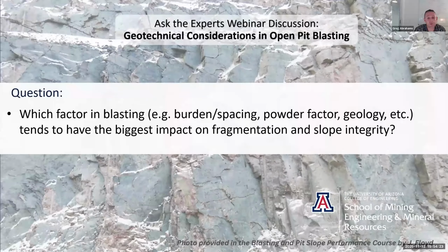With massive rock, we will be tempted to tighten up that pattern and put more energy into it, improve the fragmentation, but it will come at a cost. And at some point, that cost will be diminishing returns. And also, depending on the processing, you may not want too many fines, as that can have issues on the recovery side of things.